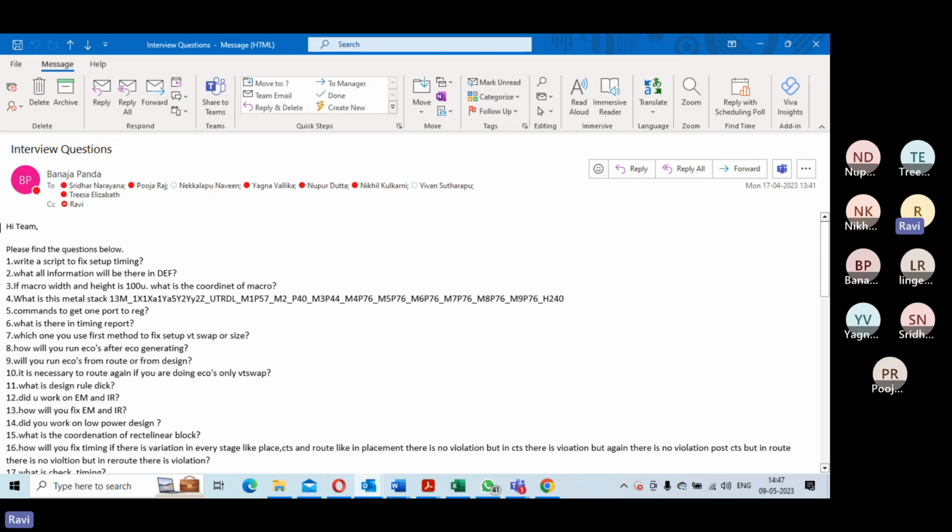Okay. So size the cells, weak drivers, which have large delay. And also look at one thing, I told you about addressing DRV, then using clock skew. The third priority is removing the crosstalk. You have to kill the crosstalk. Because if your delays are because of crosstalk, you have to actually look at why that crosstalk is there, either move the wire or it could be because of weak driver victim. So you upsize or you move the aggressor away. So you have to take an attack on the crosstalk.